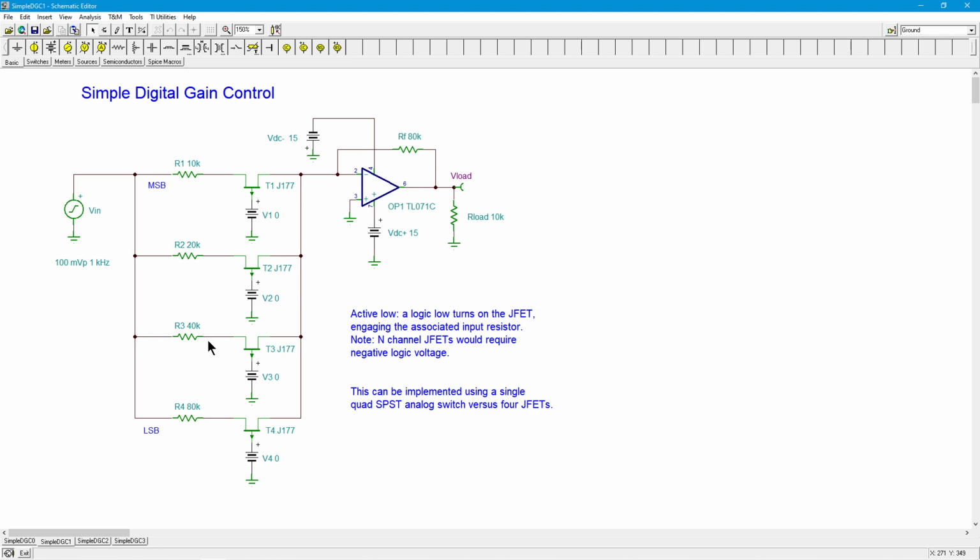In any case, the switching element over here is a P-channel JFET. And what I've done is to simulate the output from a microcontroller or some other kind of digital circuit. I just have little DC power supplies here, and I've set this up to use plus and minus 5 volts. And that's partly what goes into choosing the JFET that you want.